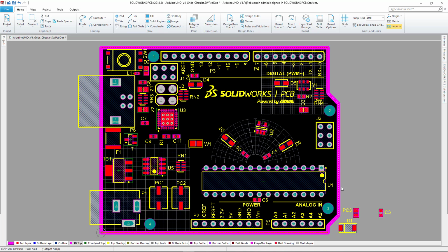Thus, the polar array grids allow us to place components in polar fashion, and it's a great productivity enhancer that allows us to place components quickly in the polar grid to satisfy boards that require either circular or radius placement. Very powerful and easy to set up and use.